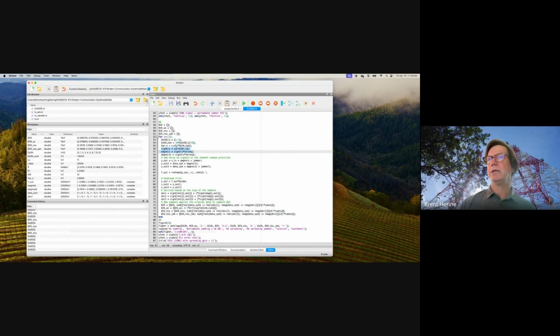they do it kind of manually here. A lot of you all have done this approach in your previous assignments. But note in the previous assignments, we've typically calculated a bit error rate at a particular signal to noise ratio or EbNo. In this case, we're looping through a bunch of these so we can see how the performance changes with an increasing signal to noise ratio. So they add noise and they add a jammer to the input signal, and that creates a Y out.